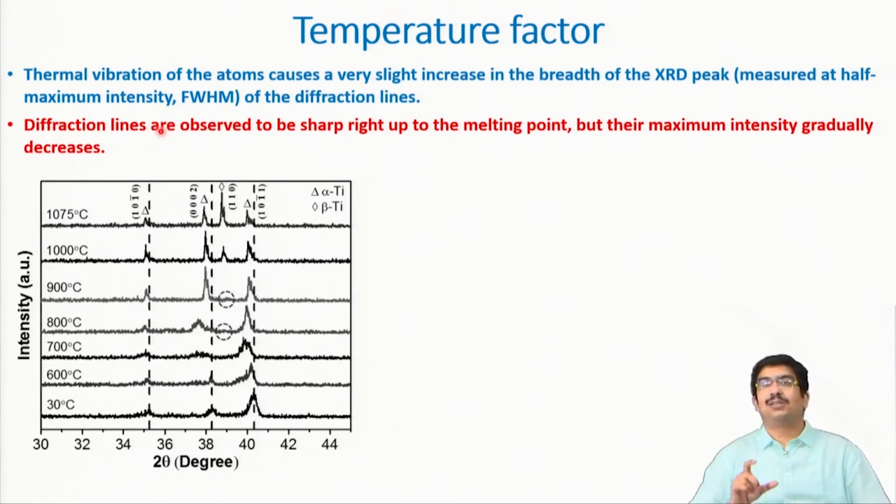And then we have seen how this thermal vibration causes a decrease in the intensity of the diffracted beam with temperature increase. When an incident X-ray beam falls on parallel atomic planes and Bragg's condition is satisfied, a constructive interference is expected, but that constructive interference doesn't happen in the perfect way; there is an imperfection, or only partial interference happens, just because of this thermal vibration.